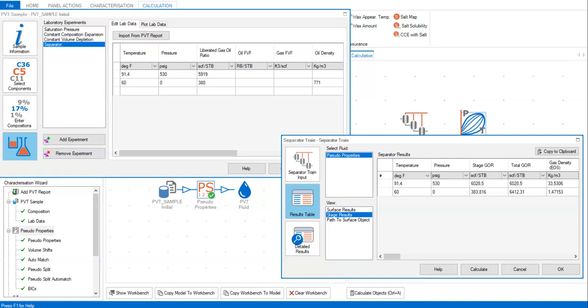For example, if we consider matching the position of the critical point of high importance, then the most important parameters you can adjust to get a better match are critical temperature, critical pressure, and binary interaction coefficient.